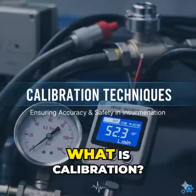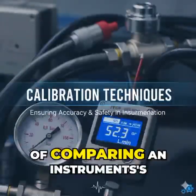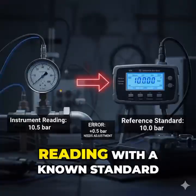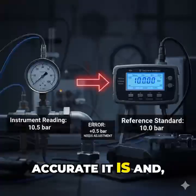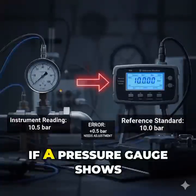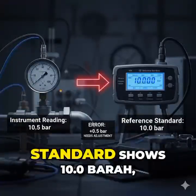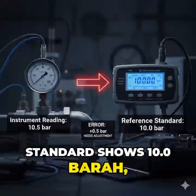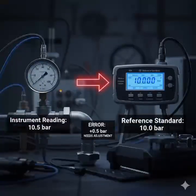1. What is calibration? Calibration is the process of comparing an instrument's reading with a known standard reference to check how accurate it is, and then adjusting it if necessary. For example, if a pressure gauge shows 10.5 bar, but the reference standard shows 10.0 bar, this means the gauge is slightly off and it needs calibration.